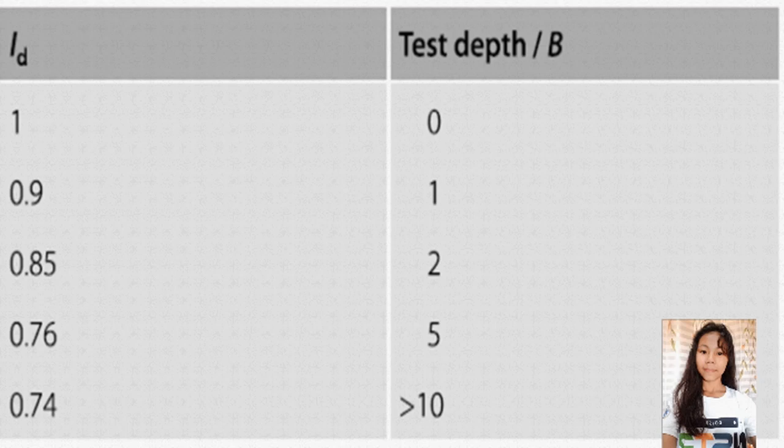The investigation of most dams includes the excavation of trial adits, and the shear tests make use of the roof and walls of the tunnel for the reaction to jacking. It is notable that in figure 6.6, the shear force is directed slightly downwards rather than horizontally.